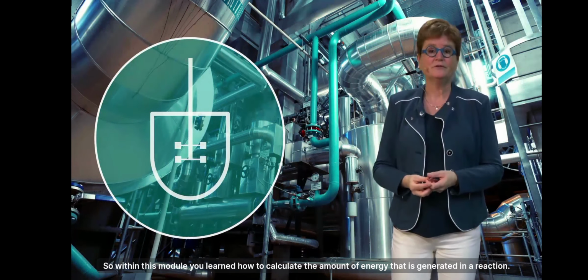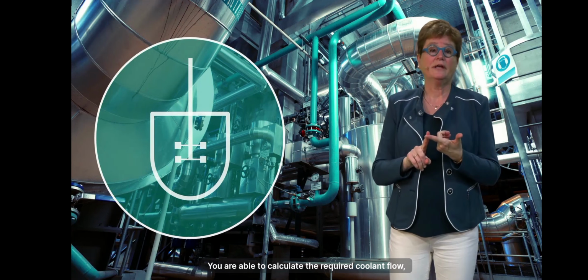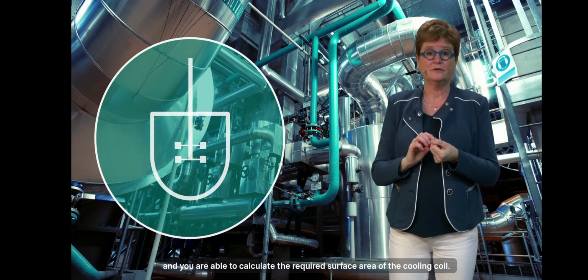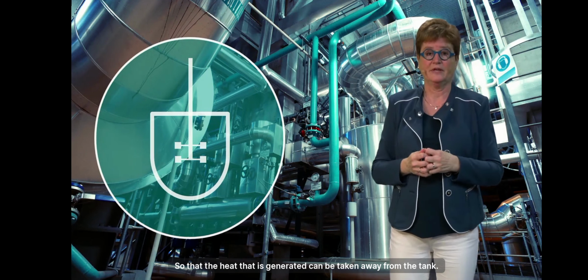So within this module, you learned how to calculate the amount of energy that is generated in a reactor, in a reaction. You're able to calculate the required coolant flow, and you're able to calculate the required surface area of the cooling coil, so that the heat that is generated can be taken away from the tank.